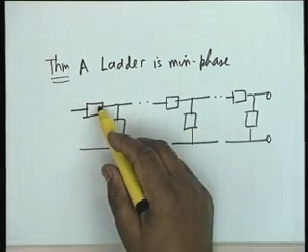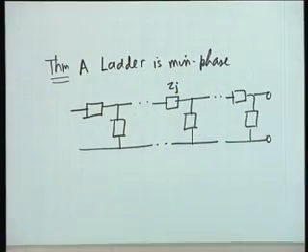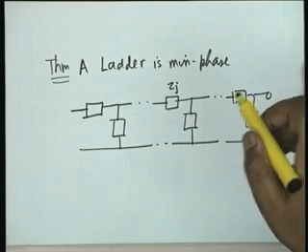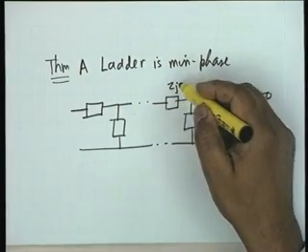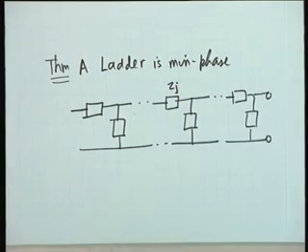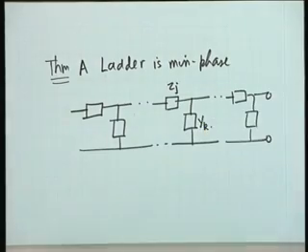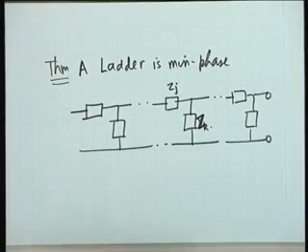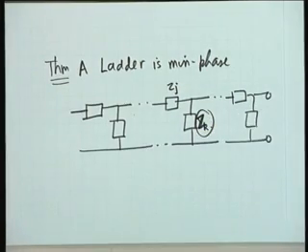Now, a series element open circuit means what? Suppose an element Zj is an open circuit, which means that it has a pole at that frequency. Right? How can it be an open circuit? That frequency must be a pole of this impedance. Similarly, if you have an impedance Zk here, a zero can be created by a zero of Zk, right?